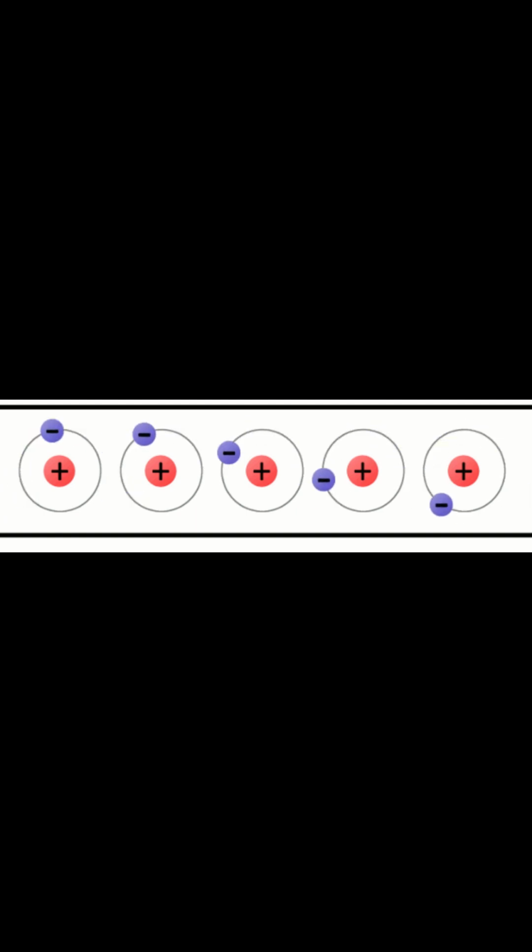Another type of circuit is the short circuit, which has very little or no resistance. It generally occurs when the conductors leading from and back to the power source become connected together. For example, a separate current path has been established that bypasses the load. Since the load is the device that limits the current flow, when it is bypassed, an excessive amount of current can flow.